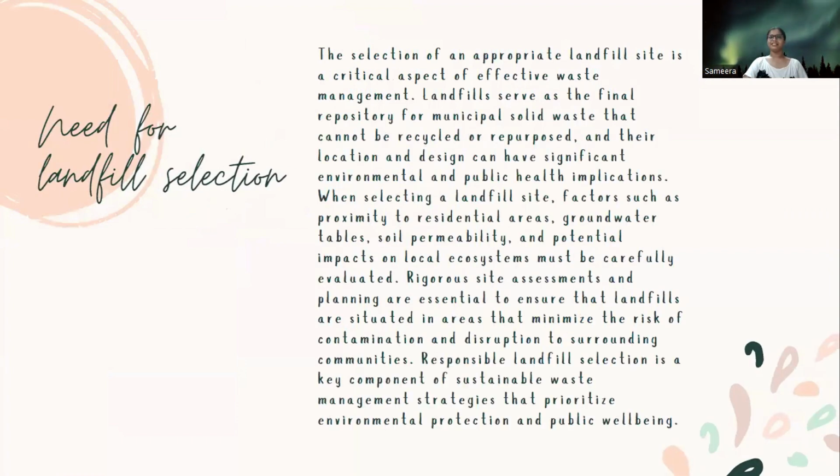Need for landfill selection. The selection of an appropriate landfill site is a critical aspect of effective waste management. Landfills serve as the final repository for municipal solid waste that cannot be recycled or repurposed, and their location and design can have significant environmental and public health implications. When selecting a landfill site, factors such as proximity to residential areas, groundwater tables, soil permeability, and potential impacts on local ecosystems must be carefully evaluated.